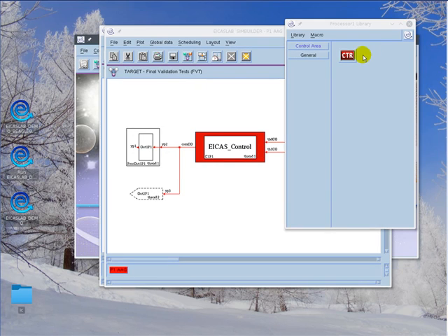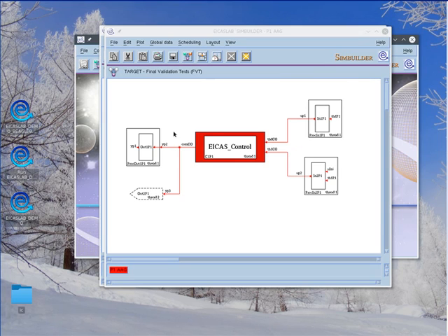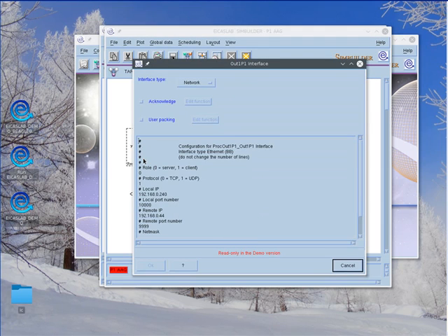All the other interfaces establish a communication between the target and the plant emulator. For instance, the out1p1 block sends the command to the plant emulator, which, as already explained, replaces the real plant in this demo, allowing us to perform final validation test trials without the real plant. It is an Ethernet interface of type network, having the role of server and using the UDP protocol.